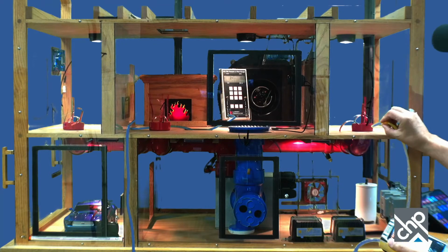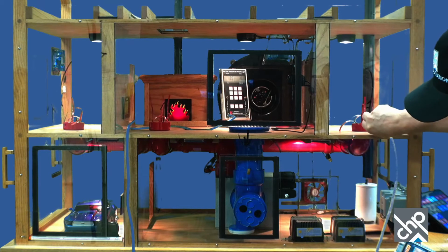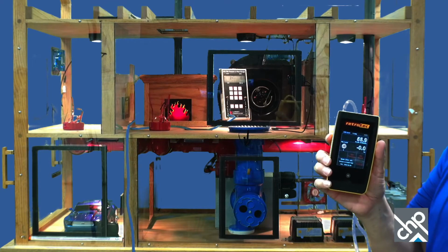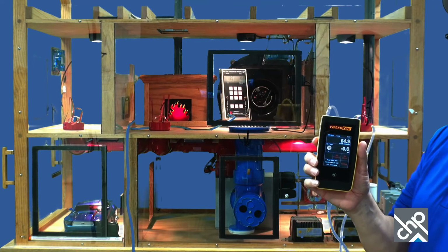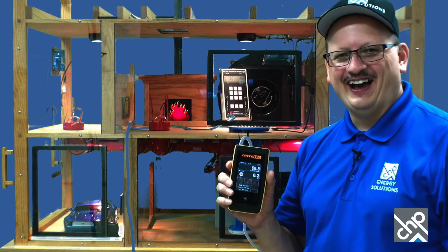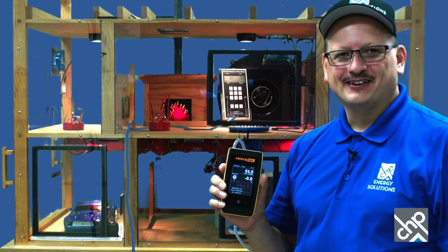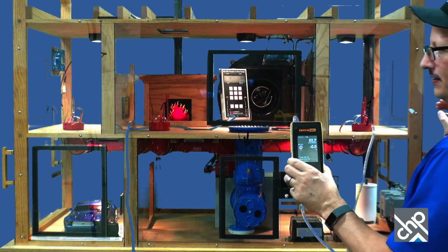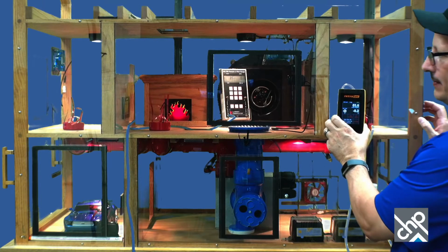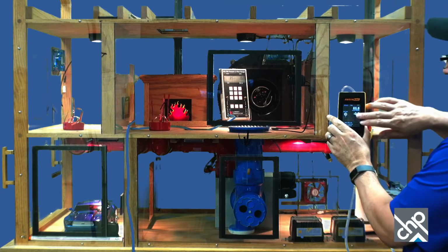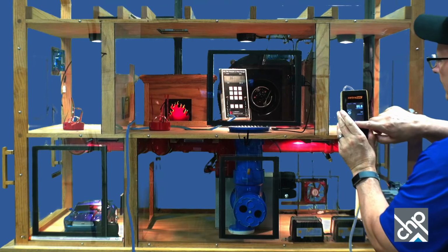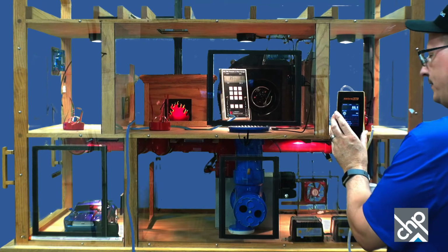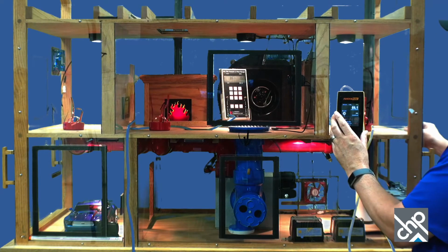But I can actually take another manometer here, and I'm on the outside of the building. This number is going to kind of surprise you. Hopefully you can see this. That's 55. So it's a really small house, and I got a lot of airflow going into that room. So now watch when I open the, I'm going to put this right here. Maybe that'll show up. We're in the 50s. Now that's the top number. Oops. That's the top number right there. And then the -4 over there, that's the pressure in the house. So in the living room.